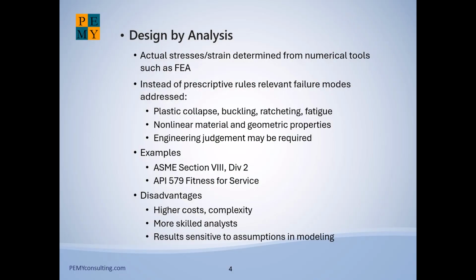The other term is design by analysis, which can replace prescriptive rules using detailed numerical calculations of stresses and failure modes with tools like finite element analysis software. Design by analysis underlies the basis of ASME Section 8 Division 2 and API 579 Fitness for Service. However, design by analysis requires more expertise and is highly sensitive to modeling assumptions. It's also more difficult to audit and peer review than design by rule methods.